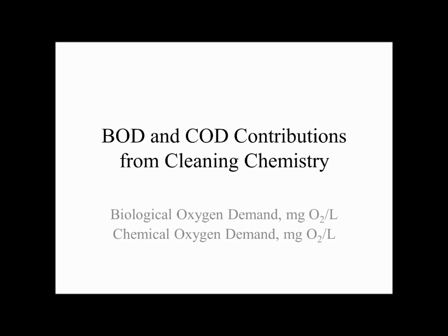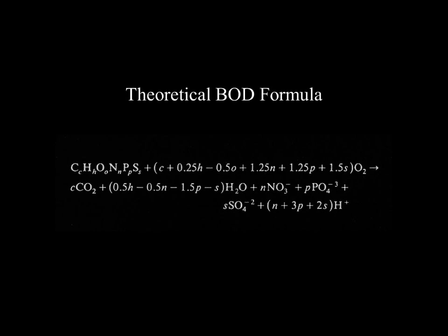I'll put them in only in case of a discussion of how to calculate BOD and COD from the organics. It's only if people are trying to really understand why BOD in wastewater is what it is. But in an inorganic world, that would be zero. And that's the beauty of peroxide. There would be no BOD contribution.